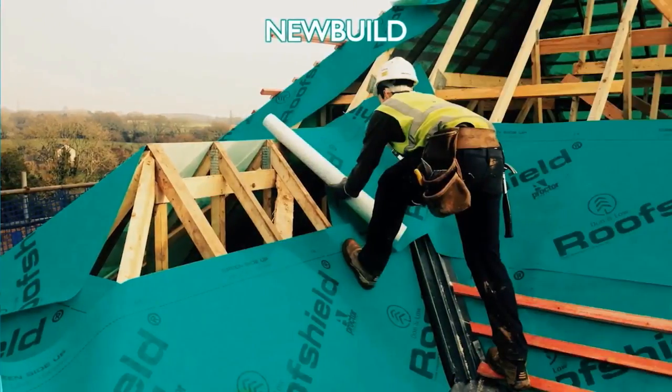On paper, new build presents far less problems. However, designers have to bear the practicality of installation and site conditions in mind when detailing condensation control measures. It's easy to draw a detail which is completely unachievable in reality, even assuming the contractors are sufficiently skilled and aware of the importance of vapour control.